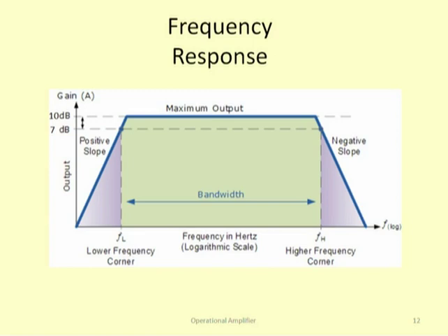If you take the ratio of 10 raised to 5 to 10, you will get 10 raised to 4. This is a very wide range. But if you convert these values into decibel, 20 log 10, you will get 20 dB, and 20 log 10 raised to 5 gives 100 dB. So basically the range was initially 10 to 10 raised to 5, but now it is shrunk to just 20 to 100, and it can be easily plotted.